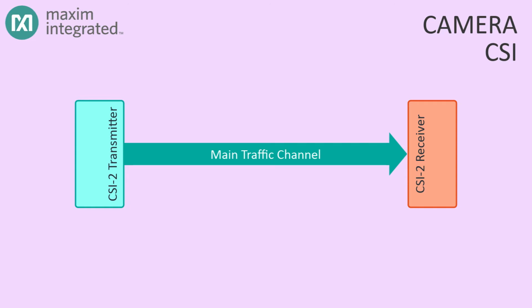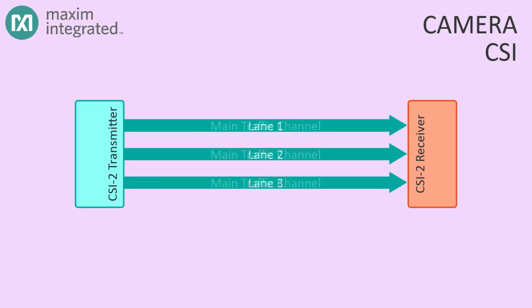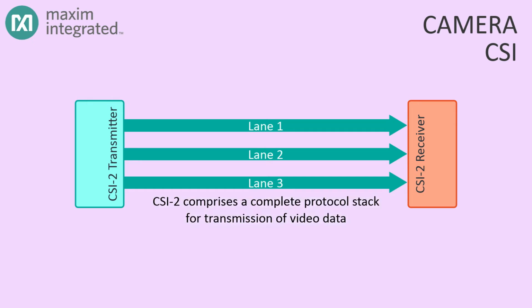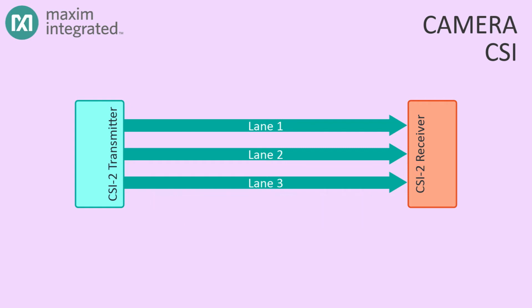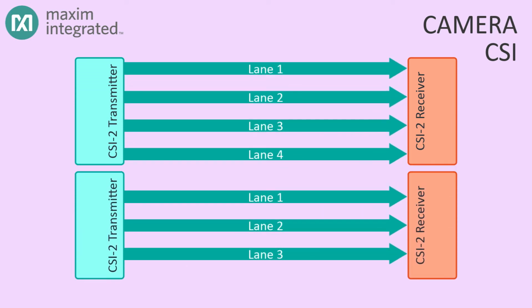First, understand that the CSI2 video path is not parallel. It's kind of a multi-lane serial arrangement. Each lane carries a portion of the pixel data, just transmitted serially. Well, simple, you might think. It's just like parallel, except we serialize the lanes to reduce the number of lines from the camera to the serializer, right? Well, no, not even close. CSI2 is a complete protocol of its own, running on a physical layer that may be one of two distinct types, called DPHY and CPHY.